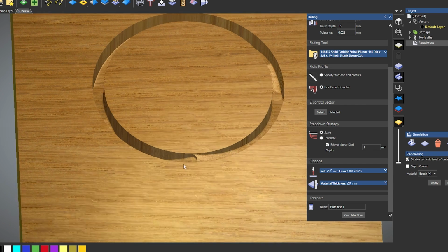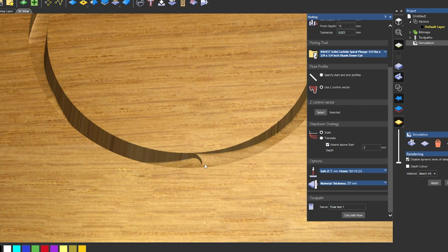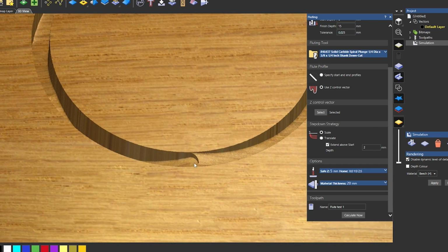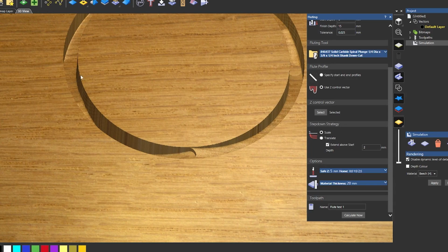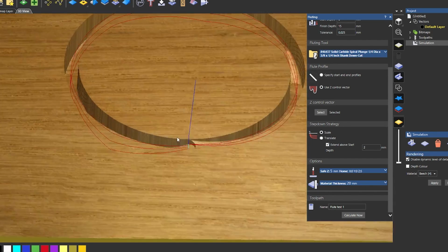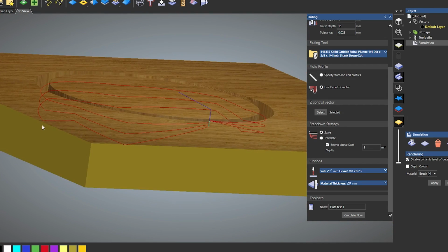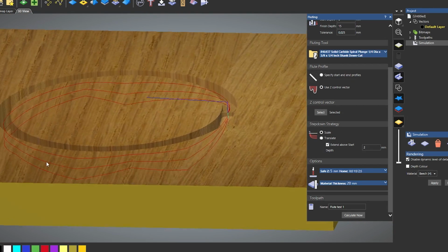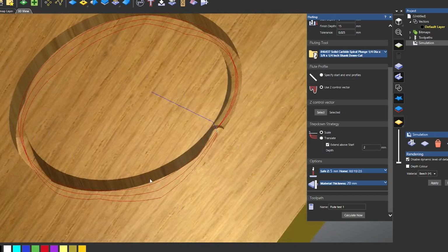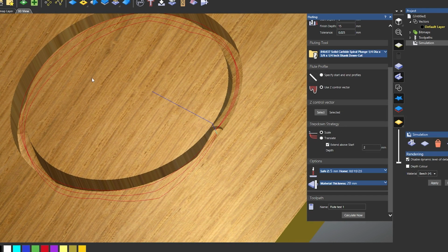And if you're wondering what the slight step is down here, this is where the toolpath effectively starts and finishes. Because they were at two different heights, that's how it's calculating. If I turn the toolpath lines on, you can actually see the difference there when I start to rotate it round. But ultimately, all of those zigzags that we had are all in there with the toolpath, just cutting around in the circle. And it would be no different for any shape that we drew.